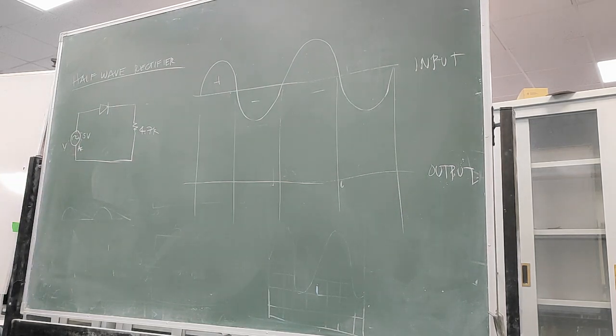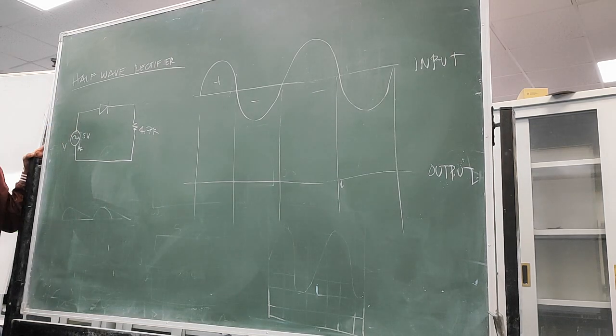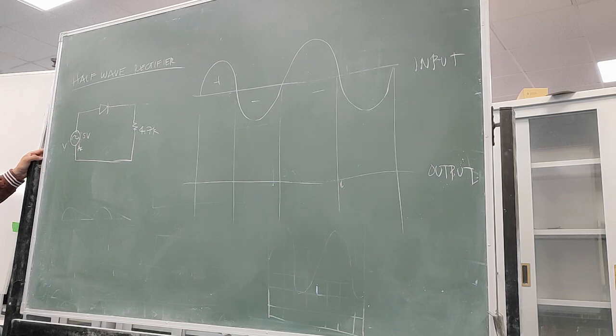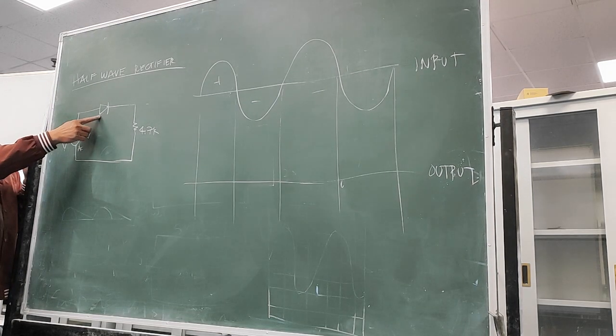There are some circuits which are also half-wave, depending on the connection. In full wave there are two ways you can connect. You can use 4 diodes, or you can use 2 diodes, depending on the transformer and so on. I think the next lab will be full wave. You'll find there are some variations of the circuit when it comes to full wave. But in half wave, they are using one diode only.